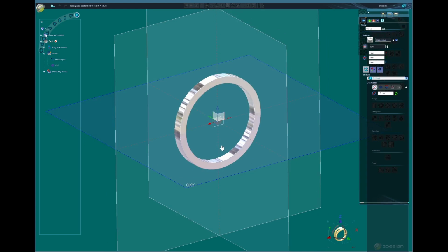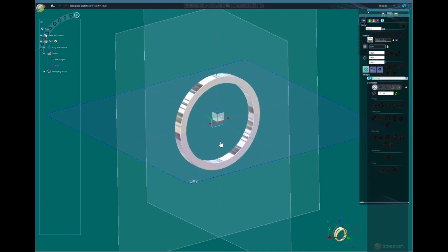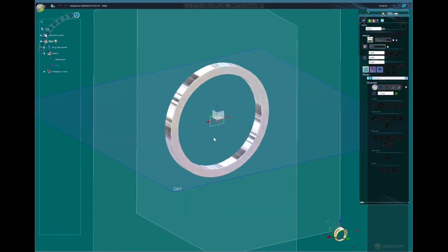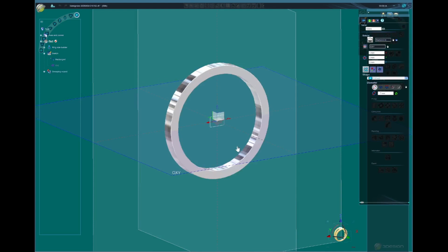Reason is, some printers, like my printer, it has a shrinkage. Some printers don't. Some casters say that their cast shrinks. Some say it doesn't. So it's very hard for you to decide what you're gonna do, for whom you're gonna design. Because I design and print my models, I know that my printer shrinks. I already leave 0.2 millimeters bigger to compensate the shrinkage.